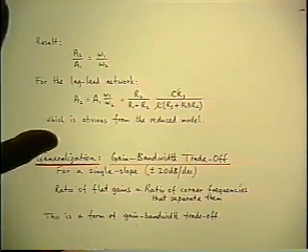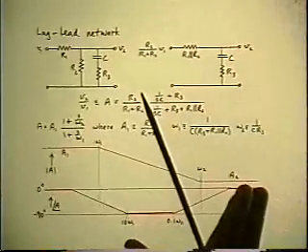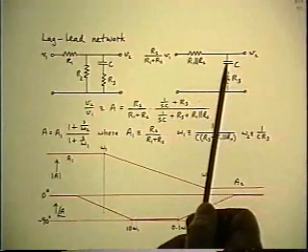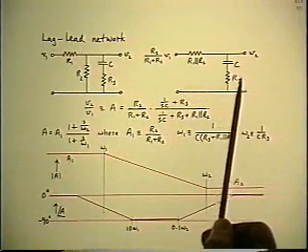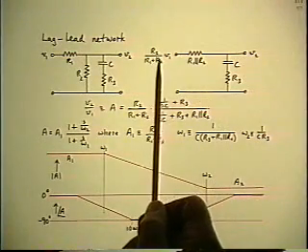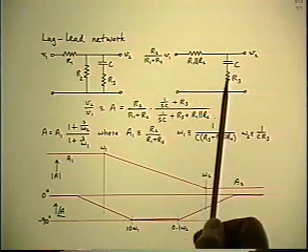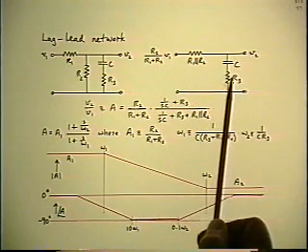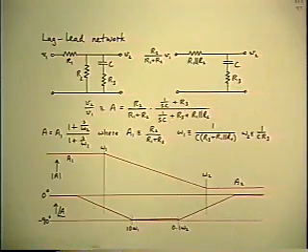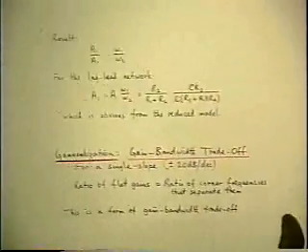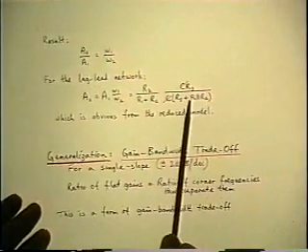It's obvious that that fits with the picture, because at infinite frequency the capacitor will be a short circuit, and multiplying the original reference gain, you will have a second divider ratio simply of R3 over R3 plus R1 parallel R2, which is exactly what this tells you.